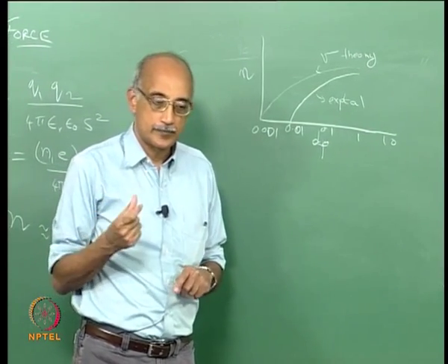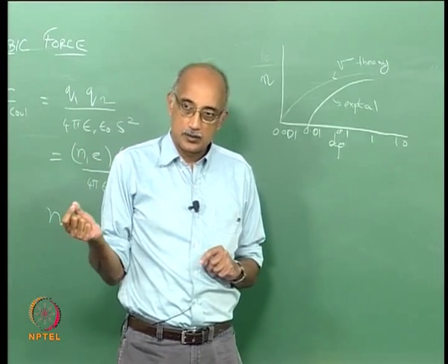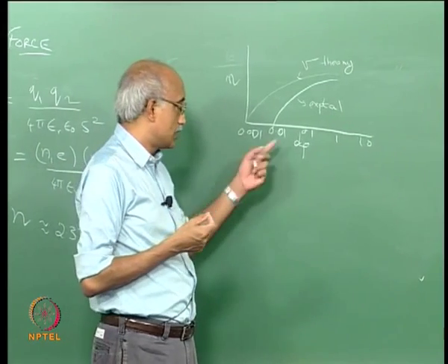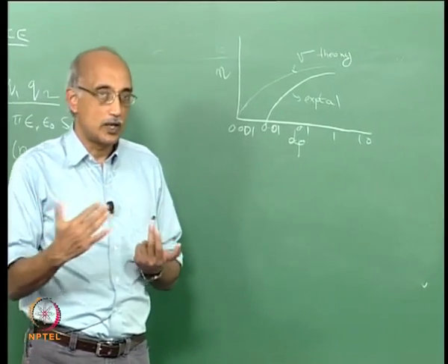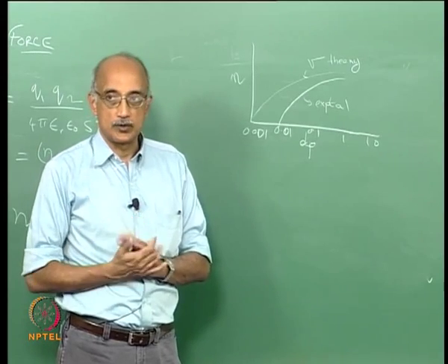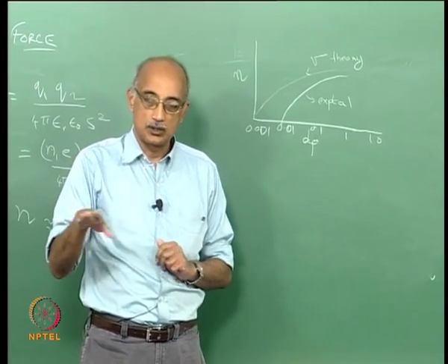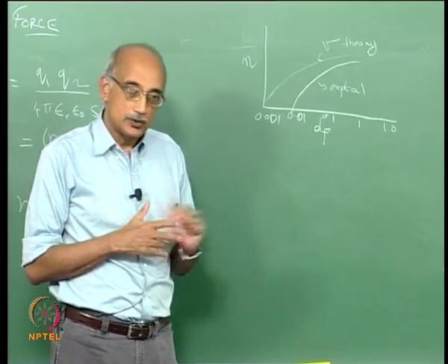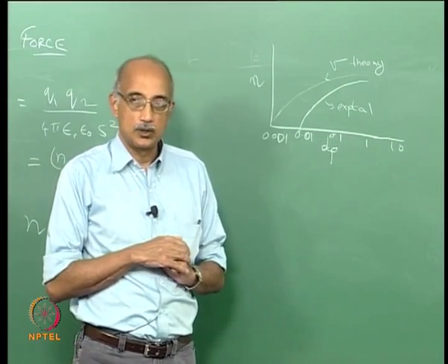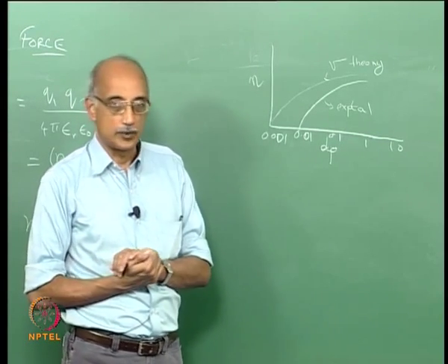So the practical implication of this, and what we have discussed in terms of Fick diffusion or Brownian diffusion, is that as you start approaching nano dimensions, diffusive phenomena become much more important than electrostatic phenomena. As you start approaching the 0.01 to 1 micron range, electrostatic effects become comparable to diffusive effects. As you exceed sizes of 1 micron, the diffusion drops quite rapidly, electrostatic effects drop less rapidly. So electrostatic phenomena continue to play a role beyond a size where diffusion stops being an important phenomenon.